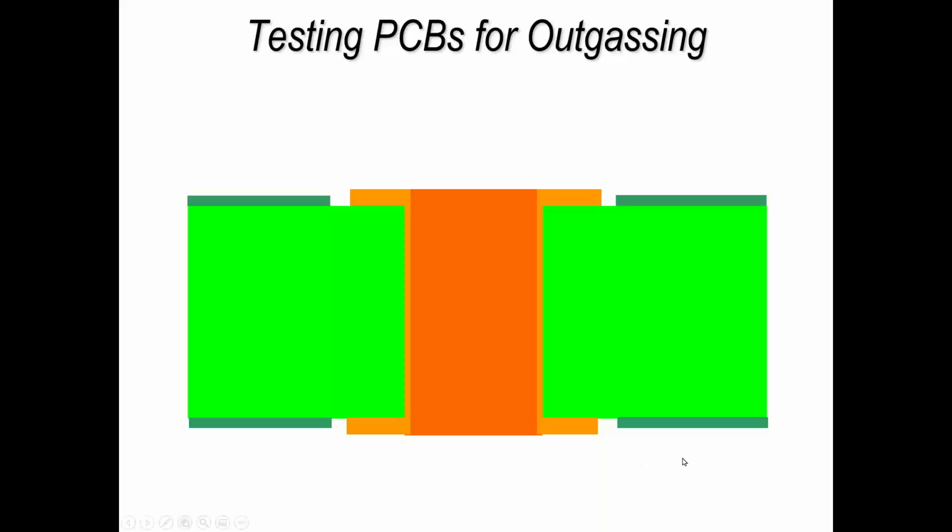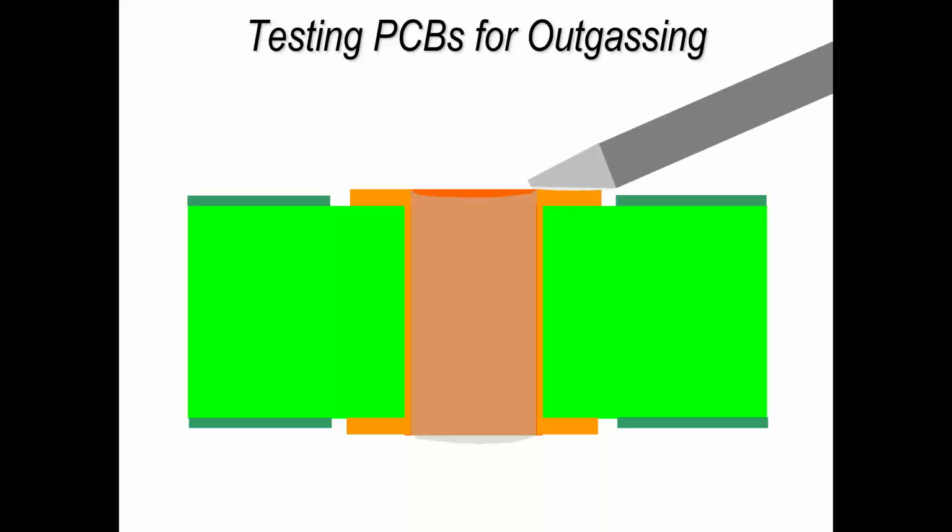And what you're looking at here is a printed circuit board that we can test very, very simply, very cost effectively for any moisture and outgassing. So I've put some oil into the hole. I then placed a soldering iron onto the surface of the pad, so I'm heating up the assembly. The oil is staying there, and what that allows us to see is the water vapor, i.e. the bubbles, coming out through the plating, through the oil. That's what we're trying to do.